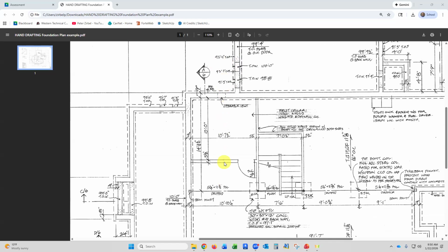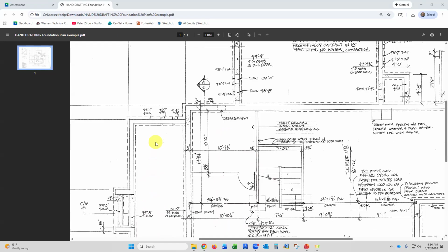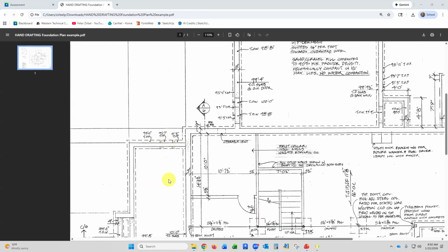And you could see now as we come down here, this is their house, and then they had a concrete porch with a slab on grade, which was just like the garage. And so I did the same thing here. That's not going to be dug out under that porch. It's just a slab with ground underneath it. But I need to keep that footing all consistent. So I stepped it up here to 93.7, just like I did to the garage. And then I stepped it up there to 95.11.